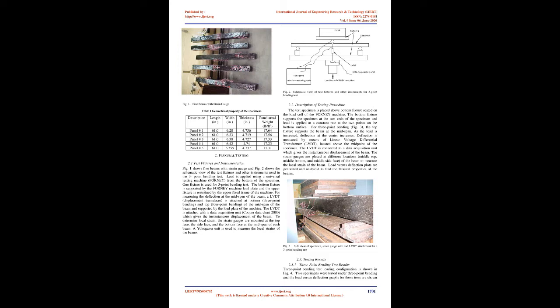Sandwich structures consisting of thermoplastic-based fiber metal laminate, FML, skins and aluminum foam core have been manufactured and tested under quasi-static and dynamic loading conditions by Villanueva [6]. The FML are based on unidirectional and woven glass fiber/polypropylene. Static tests are performed on beams of the hybrid systems using the 3-point bend, 3PB, test geometry. The low-velocity impact response of these structures is evaluated using an instrumented dropping weight impact tower.